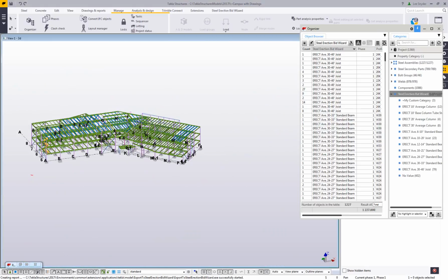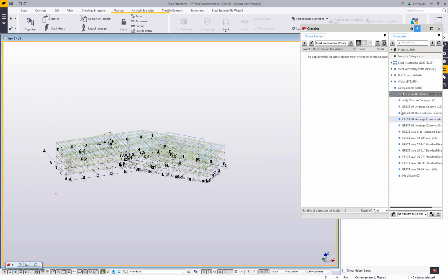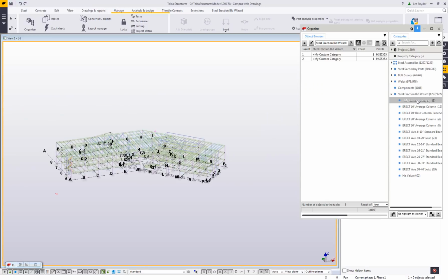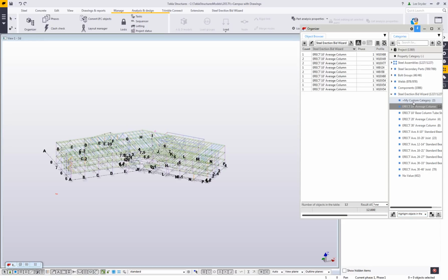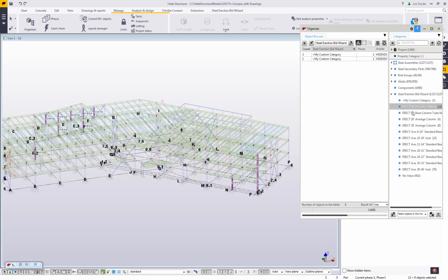And then what this does is it just makes it a real easy way to interrogate the model. So if I wanted to highlight where those three pieces were, I can just change these settings here within the model, and then I just click on these categories, and instead of highlighting, I'm actually going to select them. That'll make it show up a little easier. And then you can see that they'll just be illuminated there.